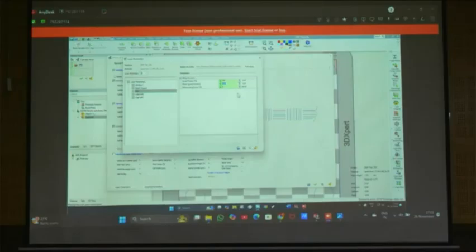So if I reduce the scan speed, what will happen? Apart from the defects and all those things, more time to scan, right? Defects you can forget, because after printing only we can see the defect, but the printing time we can see in the software itself. It will take more time, but sometimes we need to compromise on the scan speed, because optimization is there. We need to go for the less speed also to get better relative dense components, okay.